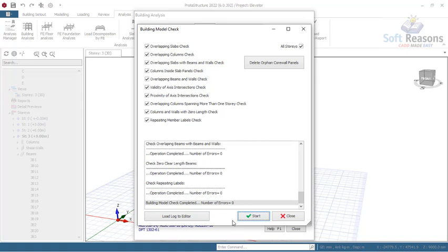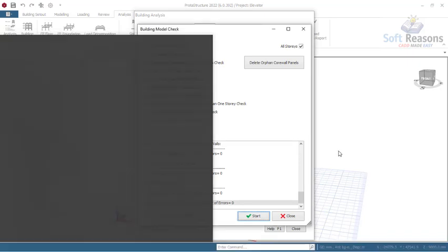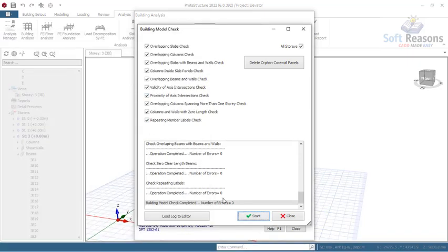I will be taking you to analysis and design now, and you will see some warnings during analysis, and I will explain those warnings. Now there's a difference between a warning and an error, so we should try to differentiate between these two. Whenever we have a warning in a structure, it simply means you can carry out your analysis and design of your structure successfully, just that there is a warning you need to take note of. But when you have an error, it mostly terminates the analysis.